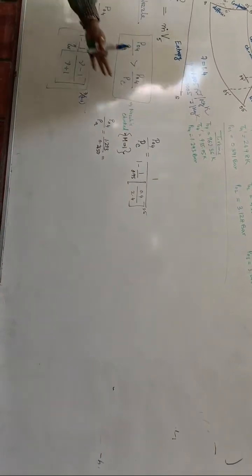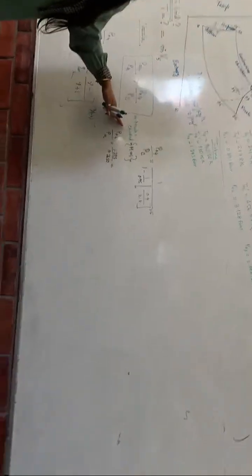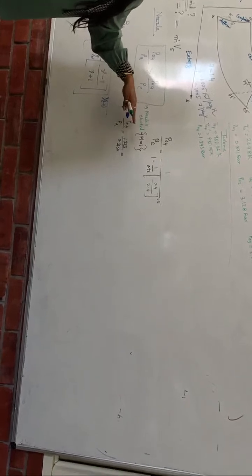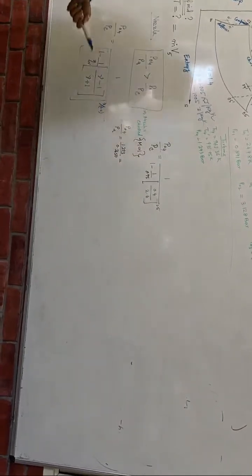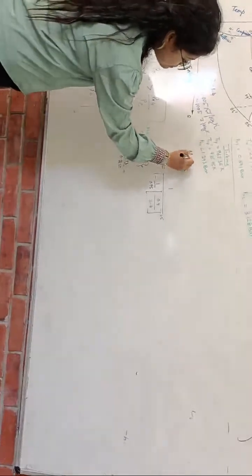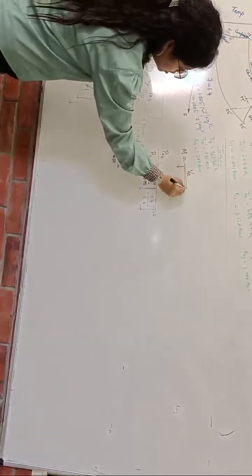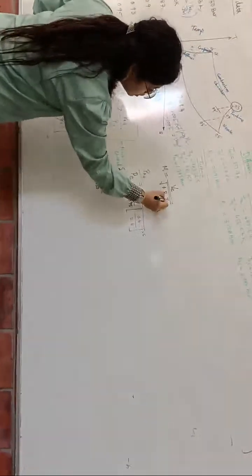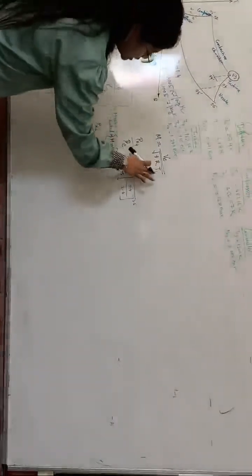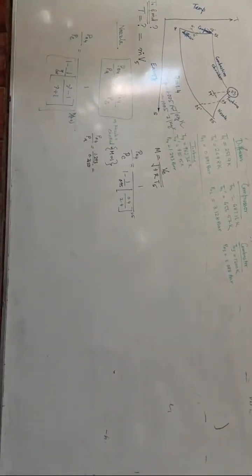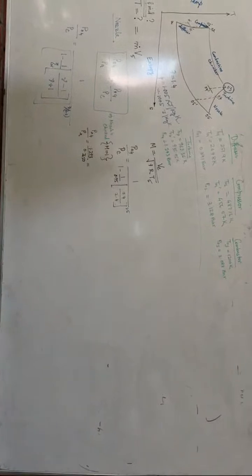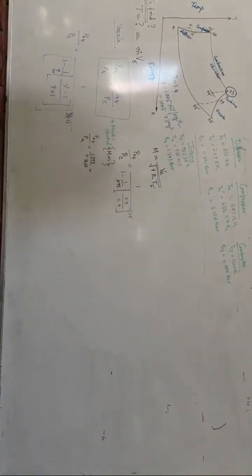That means the exit value of the Mach number, the exhaust value, is Mach 1. When I say Mach 1, what does that mean? To find VE in terms of velocity, you have to use this formula. TE or T5, you can say, the exhaust or the exit temperature. So quickly tell me whether this nozzle is getting choked or not. What's the ratio between this P04 by PA?